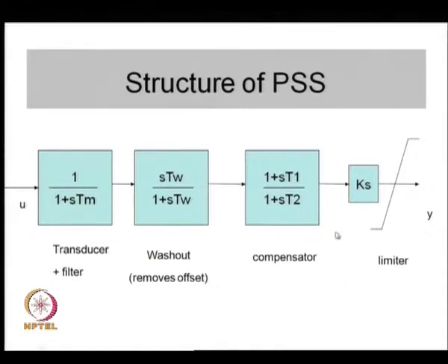It has a frequency response such that it gives a variable phase shift. If the input signal is sinusoidally varying, or if a signal is varying, this compensator changes it to some other wave shape. If it is a sinusoidal input, it will give a magnitude as well as a phase change to the signal.